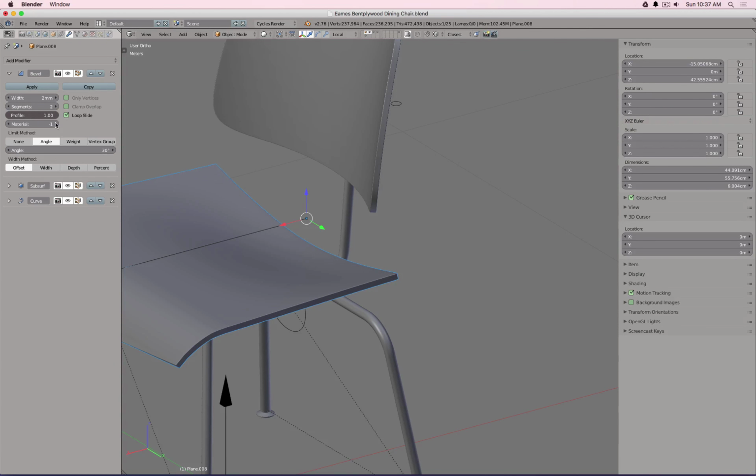And so based on what you want, maybe 2 or 1mm, that creases this edge a tiny bit more, maybe 0.5 mm. You see this is way too sharp. If we go 5mm, I see this is way too round. 2mm, 1mm, yeah, 2mm is good. Perfect.